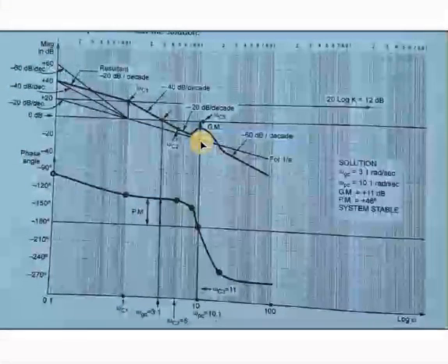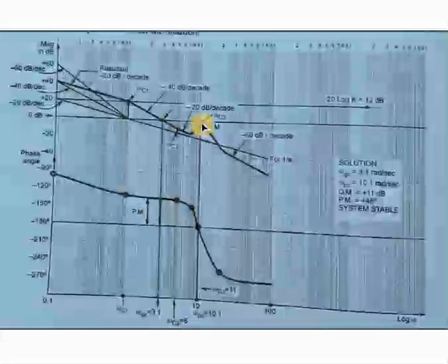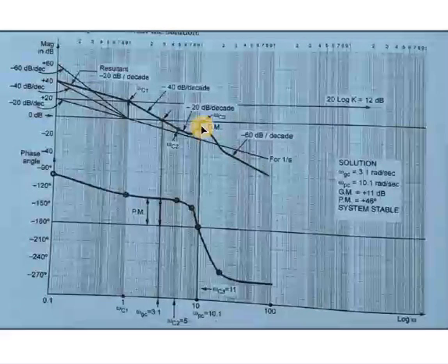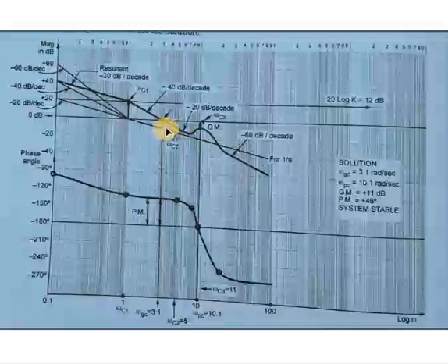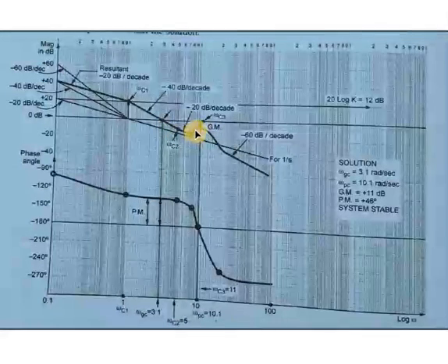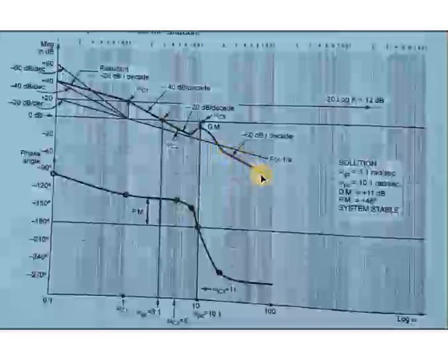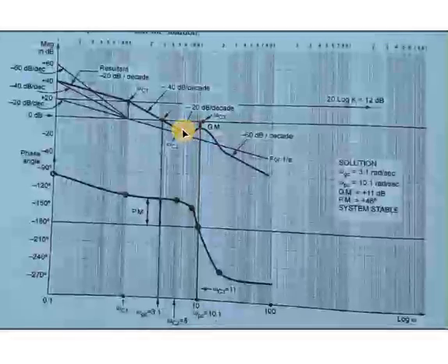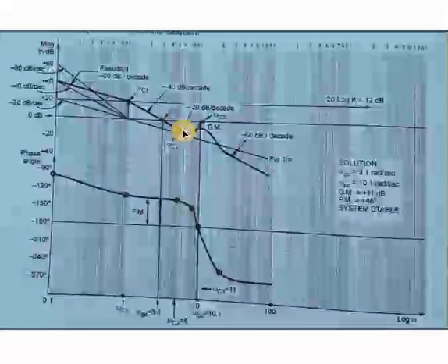Okay, and here one thing we have calculated, that the correction factor as 7.13. So at 7.13, we need to mark here 7.13 dB, and the frequency is 11 for that. So near that point you need to give some excitation, then you need to continue with the respective slope. Only that is the difference while drawing the plot if you are having the quadratic term in your transfer function.